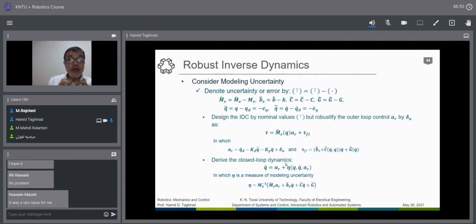If it is only plus minus 1%, this means that this resistance can be 1.01 kilo ohm or 0.99 kilo ohm. But you don't know if it is 998, it could be 992, it could be 1005, it could be anything. You don't know exactly what it is, but you know that it is limited within 1%. So it is between 0.99 kilo to 1.01 kilo.